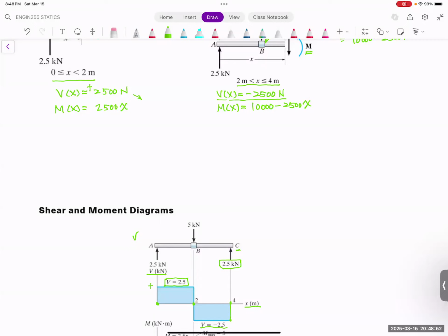There shouldn't be any shear force because there's nothing beyond 4 meter. And look back to where the A reaction is. This is the A reaction, so your drawing is going to go up if you have a supporting force going up. If it is not going up but going down, then it will start from a negative value.